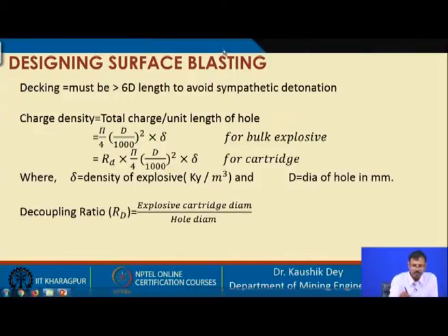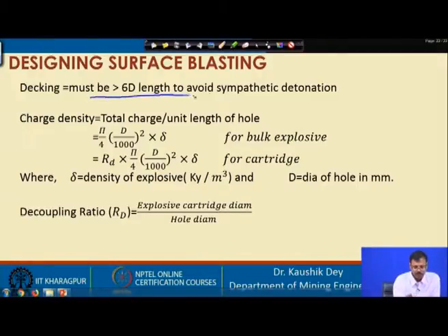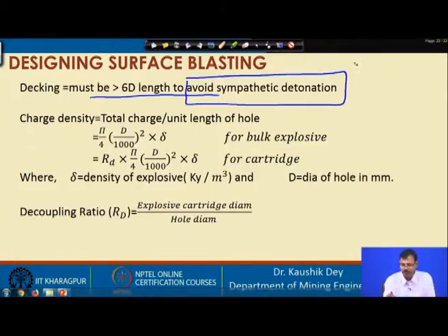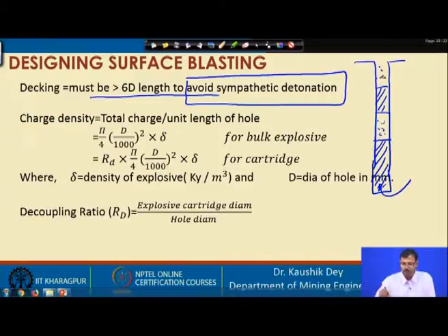Deck charging may be carried out, and the deck length must be greater than 6 times the diameter, so that sympathetic detonation can be avoided. That means, if this is the whole section of the hole, this is the first charge which is being blasted, then some deck material is provided, then the second charge is provided, and finally, the stemming is provided.